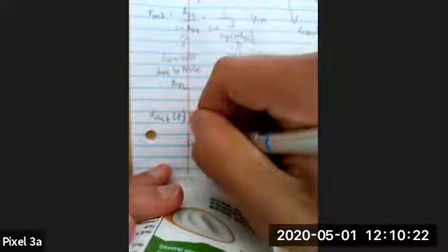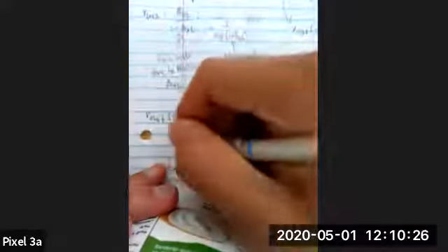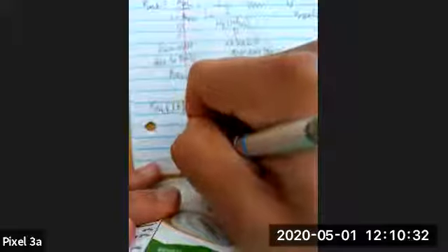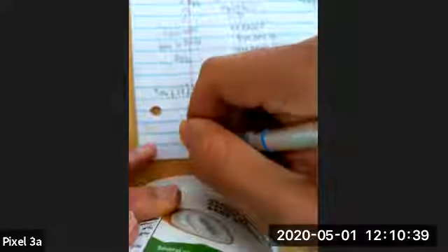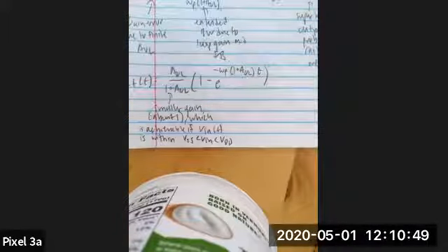And so in this case, we see that we have a smaller gain, which is about 1, which is achievable if the input voltage as a function of time is within VSS and VDD. And that's usually a reasonable assumption to make.